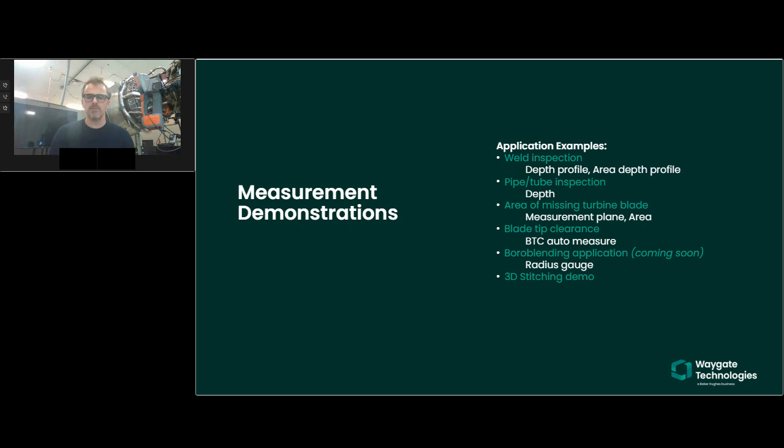Yes, I'll be taking you through a number of interesting examples or applications associated with a variety of measurements. I'll be really focusing on 3D phase measurement, not traditional or 3D stereo that you've heard Clark provide an overview of. So I'll be spending the next 20 to 30 minutes talking about these points here: weld inspections, pipe tube inspections, measuring missing areas of material, for instance going through that from a gas turbine inspection application, and blade tip clearance, a relatively new measurement that is now available in 3D phase measurement.